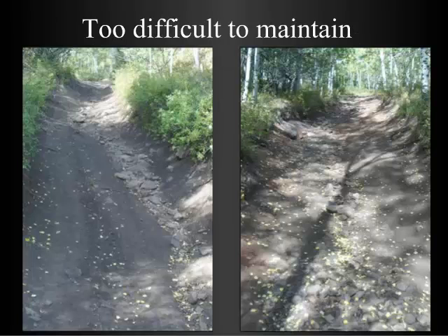This is on Trustland's Tabby Block, the McDonald Basin reconstruction project. In this particular case, a road went from the bottom up to the top. And in places, the grade wasn't too bad. But you can see here that this is basically a stream bottom, a valley bottom. And there's just absolutely no place for the water to go. In this particular case, these slopes are over 20%. So the combination of valley bottom location and the slopes, to me, it was really easy. You're not going to reuse it.